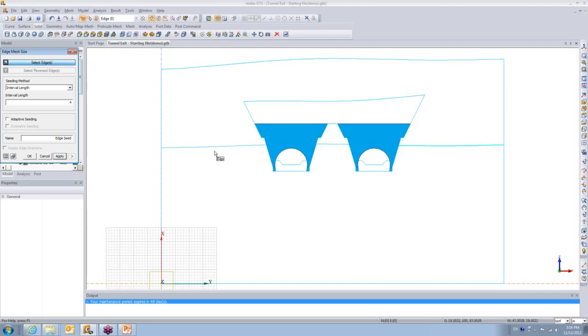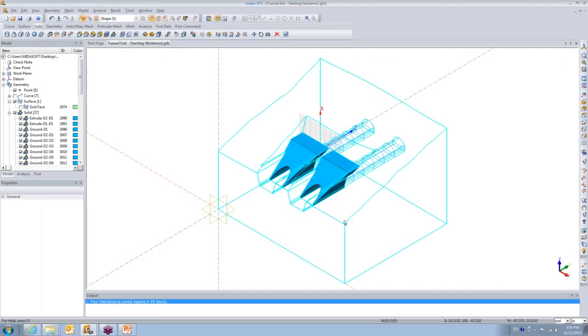And there is another way of controlling the mesh size. Let's say I want to apply it as a linear gradient. So I'll select the edge, let's say this one, and the reverse edge as this one, and in the starting I want the divisions to be of length 10 units, and then towards the end it should go to 4. So this means if I hit the preview button, you can see the distances are higher here and that they are getting denser towards the end, and then I can say OK. So internally the program knows along these edges what mesh size it should obey.